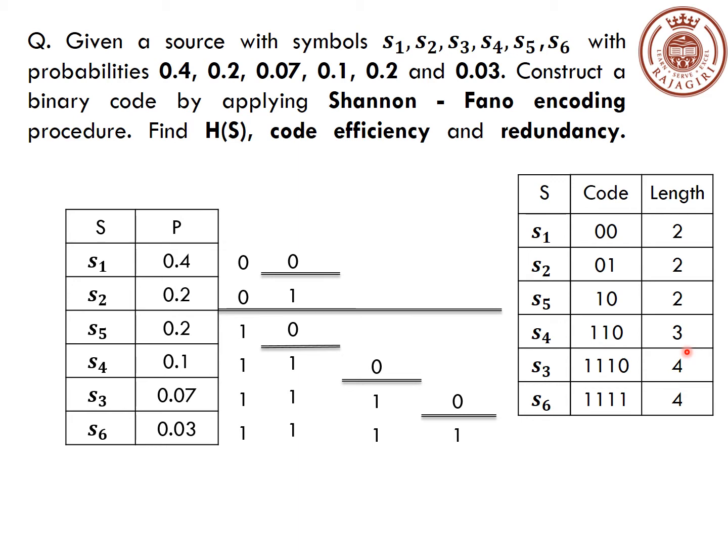Now the concept is satisfied here. What we discussed earlier, we said that the symbols with maximum probability should be assigned lower code lengths, whereas the ones which occur with least probability have to be assigned maximum code lengths. With that, we can assure that the average word length is going to be minimal, because if the ones which occur with least probability are assigned maximum code lengths, I can make sure that the average word length will be at an optimum level or will be less.